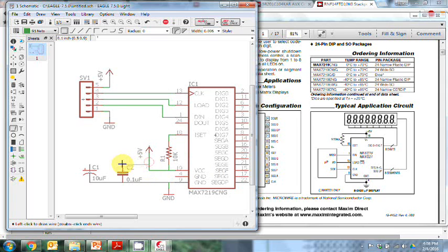And I've got a bunch of wires all kind of connected around, and the thing is, some of these wires cross or meet at a join, and without this little junction tool, these little dots that I'm putting down, they're not actually electrically connected. If there's more than one wire at a point that meets, I have to make sure I put this junction down, and what that does is flatten the diagram. It actually makes those wires connect.